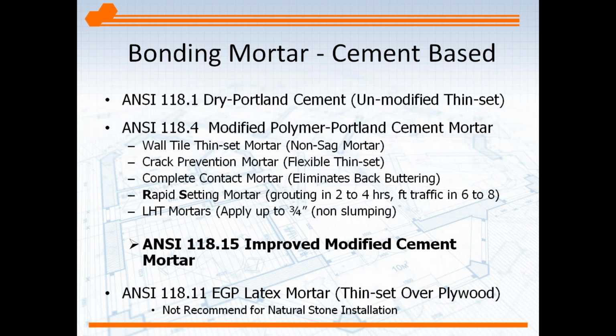And 118.15 is used quite a bit above grade, especially when a crack isolation membrane is not used above grade. Stairs, pools, anywhere where you're expecting more stress on that tile. And as the large format tile have become bigger and bigger, there is larger amounts of stress on each individual panel. So we're seeing the 118.15 specified and used quite a bit more.